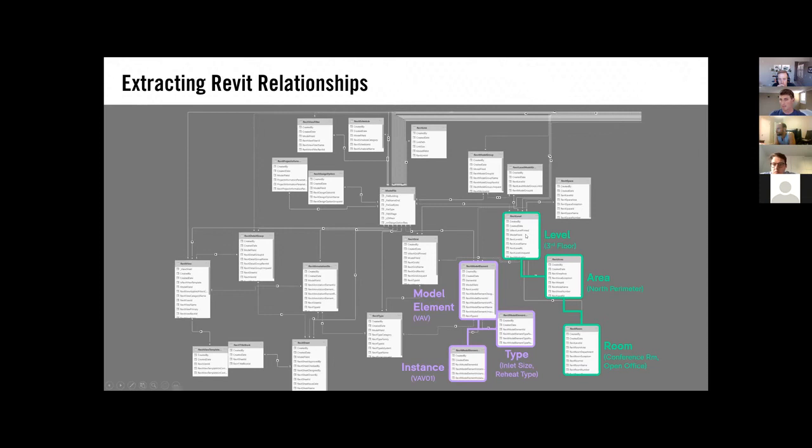So Revit, for example, has the concept of a level, an area, and a room. Rooms are contained within an area, and areas contained within a level, for example. Well, obviously those are vocabulary for now my Brick relationships. I know that an asset is contained within a certain area of the building. I know that it feeds air to certain rooms, right? So Revit, just as the authoring tool, aligns very well with some of those Brick tagging techniques.